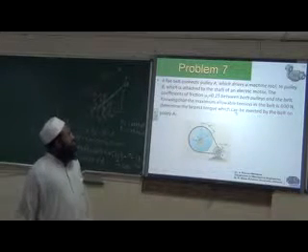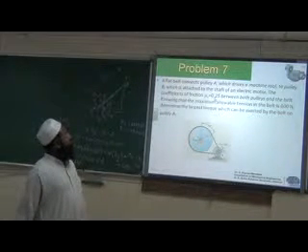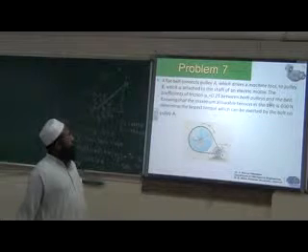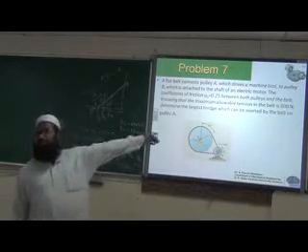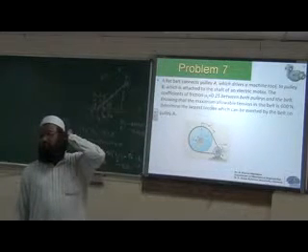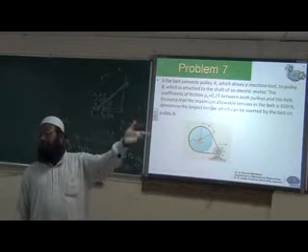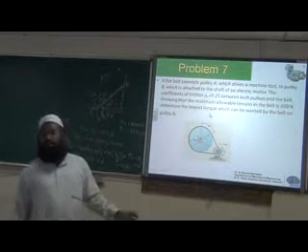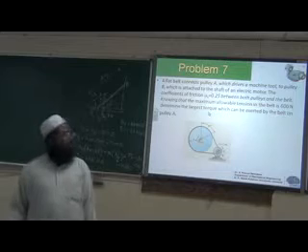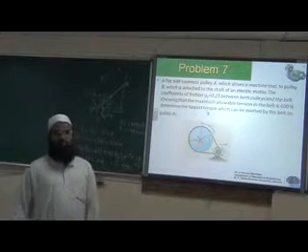So we have to find out, mu is given, coefficient of friction 0.25 between the pulley and belt is given. Maximum allowable tension in the belt is 600 Newton. So maximum tension is given. T1 is given, 600 Newton is given. We have to find out the largest torque exerted by the belt on pulley.